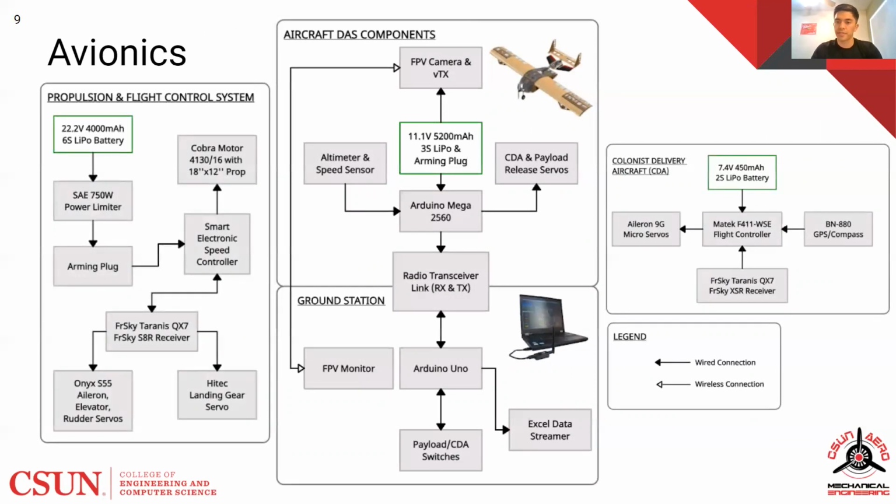Through this extensive research, these tools allowed our team to proceed with control surface design during vehicle sizing, as well as finalizing servo selection with respect to our vehicle's weight, material, and payload configuration. A new addition to our flight control system this year was a 3-axis gyro stabilization unit, which was integrated into our radio receiver controls. This was useful in preparing our aircraft for varying weather conditions and providing fast control response to different air loads. Once our selections were finalized, all results were experimentally verified during ground testing with the servos, as well as a custom designed 3D printed thrust end for propulsion.